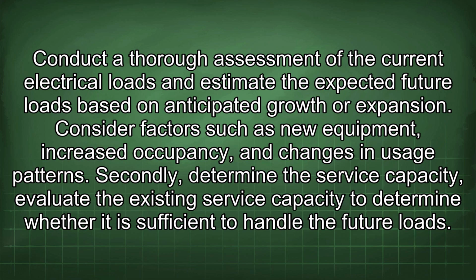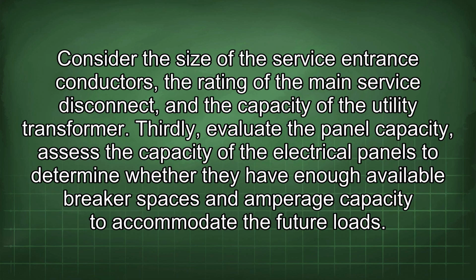Secondly, determine the service capacity. Evaluate the existing service capacity to determine whether it is sufficient to handle the future loads. Consider the size of the service entrance conductors, the rating of the main service disconnect, and the capacity of the utility transformer.